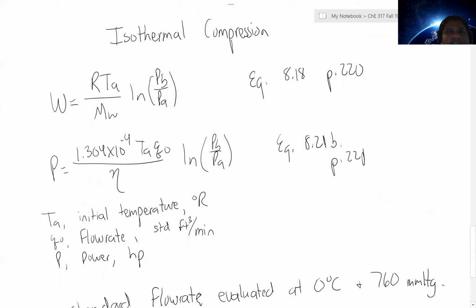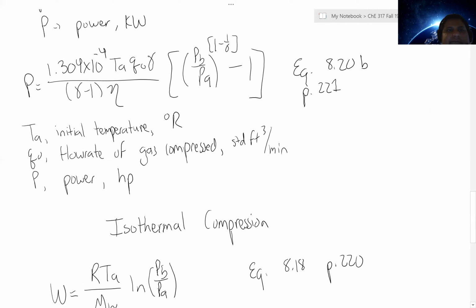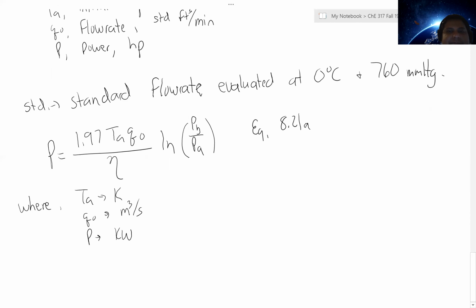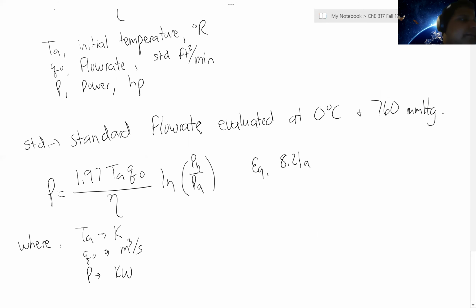So with these equations, you can get an idea of how to calculate both work and power in your systems. Now, one thing we do need to discuss is when we're considering compressors. As the fluid experiences a pretty significant increase in temperature as the gas is compressed, it's standard practice to limit the degree of compression that exists within a single compressor.